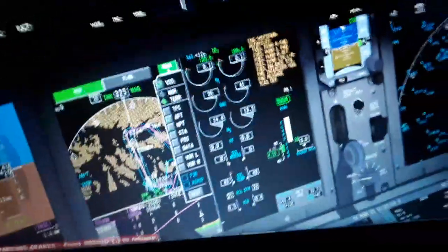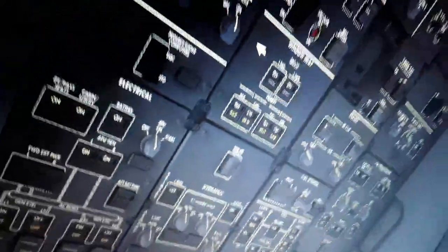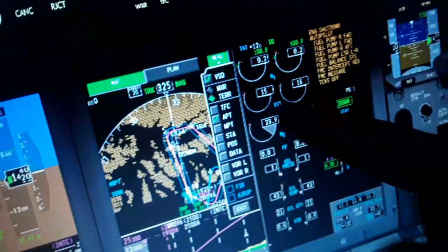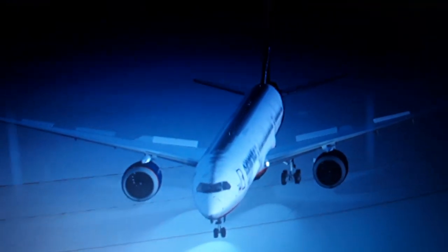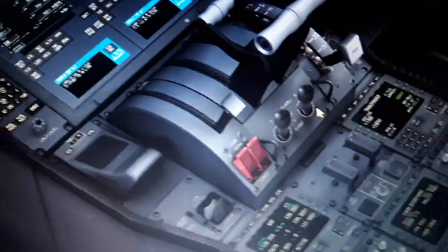Actually, you're gonna see some resets in the overhead panel, and here we have the initiation of the pressurization of the engines. Some APU pressurized air is admitted to the engines. You can see the yellows in the overhead panel here because there is a reset right now of the systems, and fuel is still off here. So above 23%, you can see we have enough pressure in the right and the left engine from the APU, and we can start the fuel flow process and the ignition of the fuel, turning on the fuel flow, left and right engine.